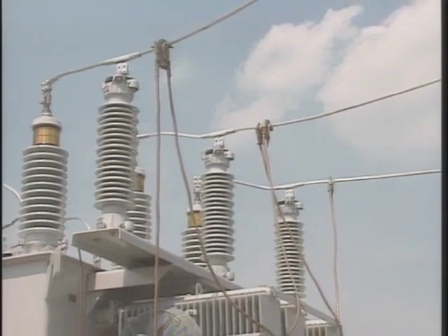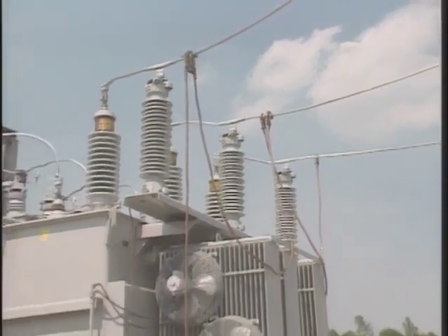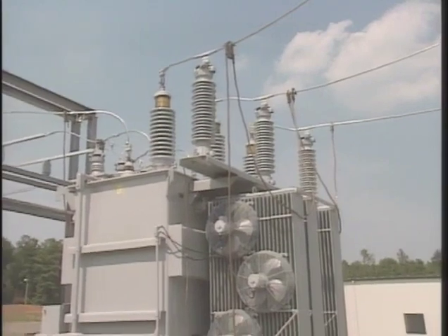In order to get useful, reliable test information, a turns ratio test has to be performed properly. This means that the transformer must be made safe to work on. The test leads must be connected to the right terminals, the test set must be properly operated, and the results must be accurately documented. We've already looked at where test connections are made. So in this part of the program, we're going to concentrate on taking the proper safety precautions and operating the test set.